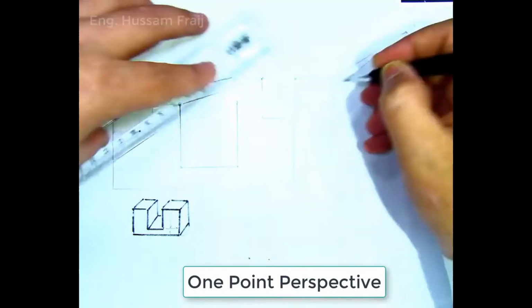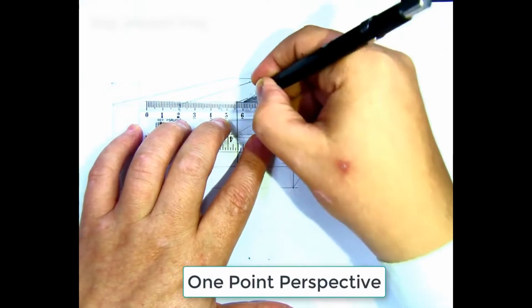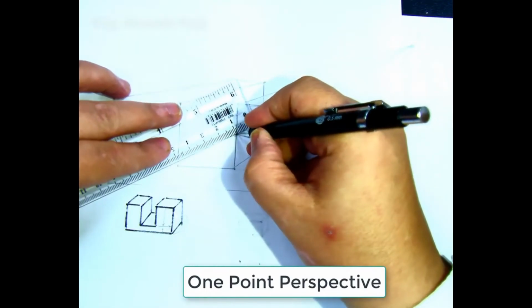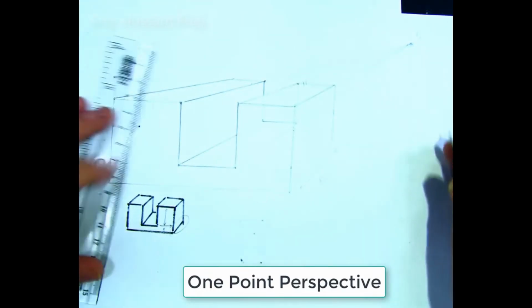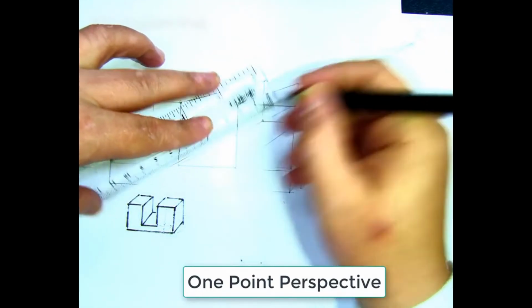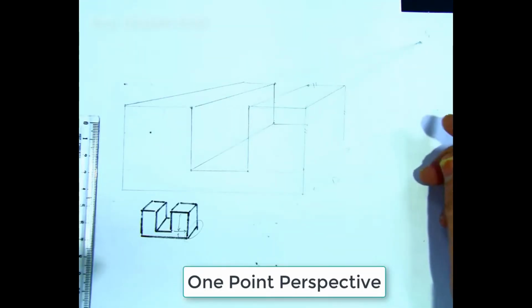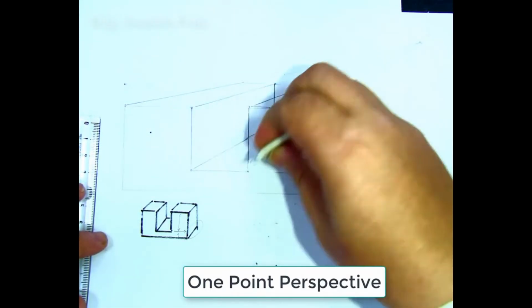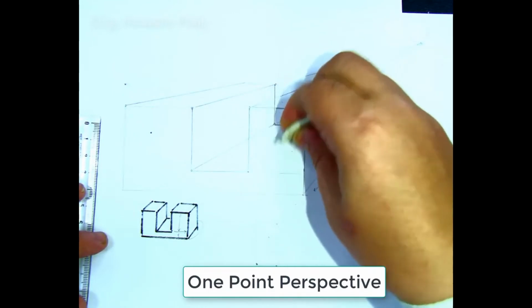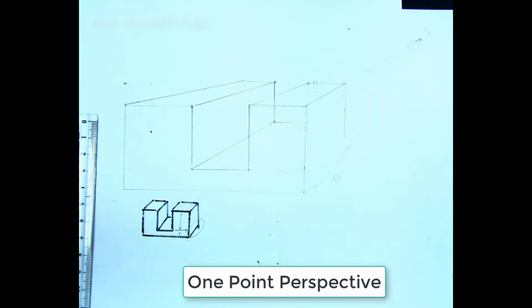Okay, this line here, and from here to here only visible, unless you want to draw it in wireframe. If you want to draw in wireframe representation, you can do this. This is wireframe. Okay, but for engineering drawing, this should be a hidden line because we cannot see it. See, all these lines are hidden. See in the back, they are hidden lines. They should be hidden. So this is the task we finished.